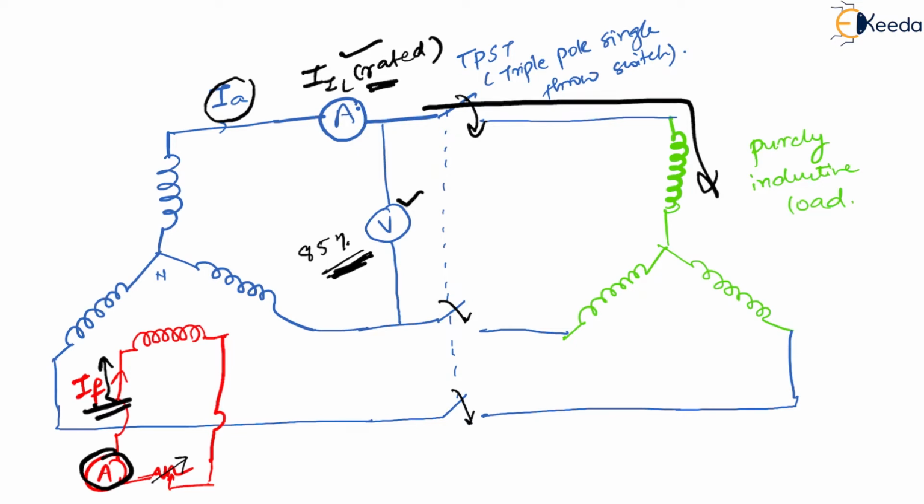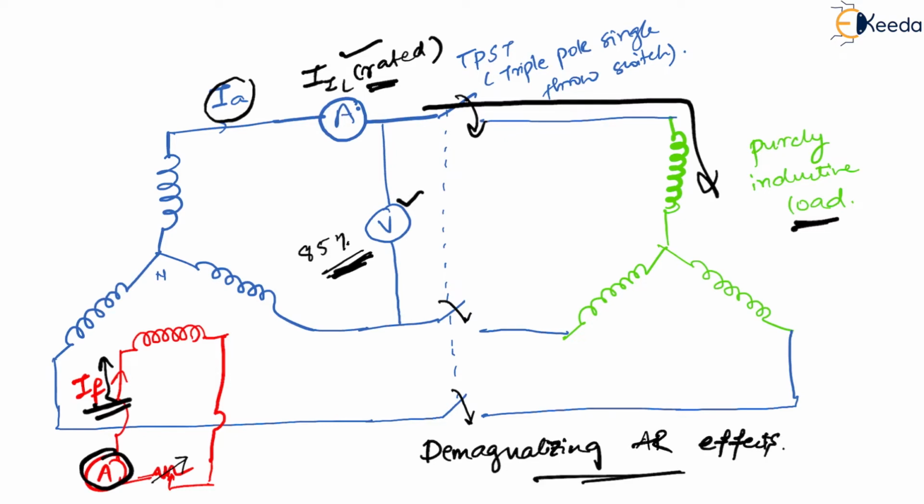Yes. Remember that this is a purely inductive load. That is the reason we call it a zero power factor load. In such a case, conceptually what happens is demagnetizing armature reaction happens, correct? We have seen that demagnetizing armature reaction effects happen, correct or not? Yes.